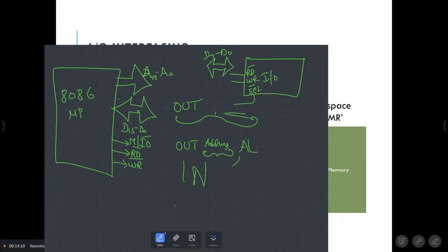Once again, here you will have a port address and data. Data and port address, that's all. This also consists of AL, comma, address. It is writing data into the AL register. We will see the syntax exactly by writing the program. That means in IO mapped IO, or what we call isolated IO, we use this in and out instruction. This is the way it writes.